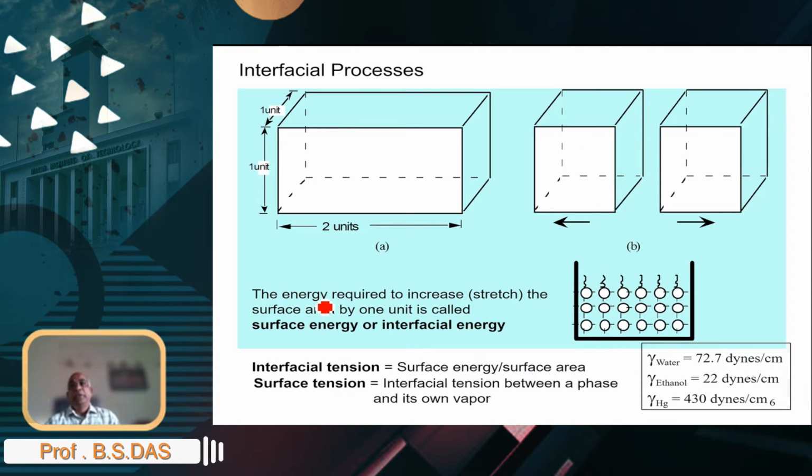So, coming back to the practical aspects of these forces, generally we disregard the van der Waals and electrostatic dipole effects on water. Most of the water that we are interested in is weakly held with the soil solids in the form of surface tension or interfacial energies and the osmotic component.